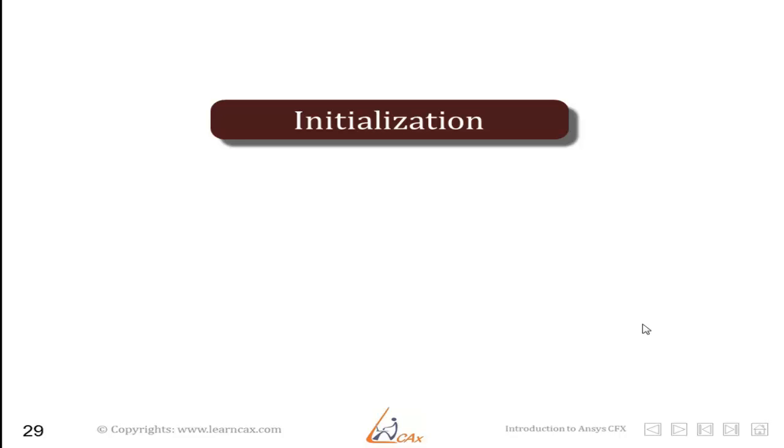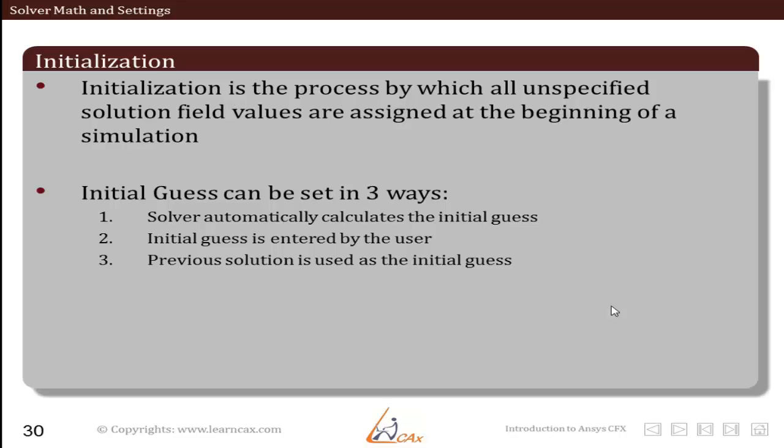So now we will see what initialization is, what we mean by initializing a solution, and how to conduct initialization of a solution within CFX. This is an extremely critical area in order to start and progress your simulation calculations, and it affects your simulation from various angles. It can make your simulation diverge, as well as lead the simulation to take a longer time to produce results. So it is a very important area which decides how your simulation progresses.